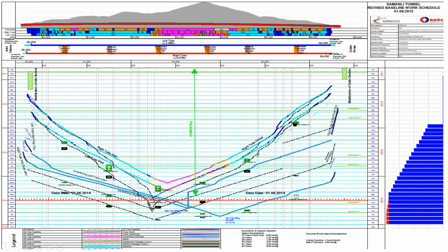Here you can see one crew is starting from the left tunnel. The second crew is starting here, so 2 crews are working from one side. Again, on the right side, there are 2 crews working. For the 2 tunnels, we also need to keep some distance, like 300 to 400 meters, because of safety. Because of safety, you cannot work both tunnels in parallel at the same time. According to many international rules and country rules, you need to keep some distance between the 2 tunnels.